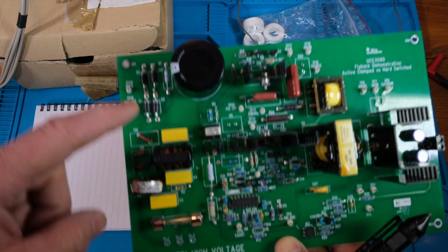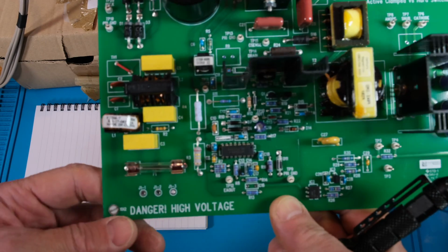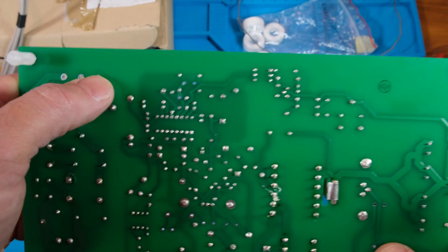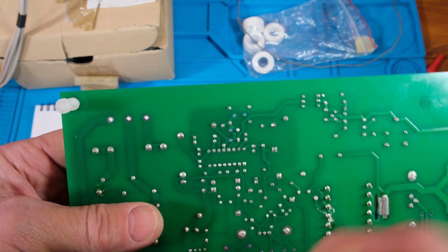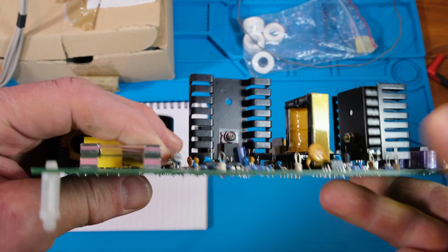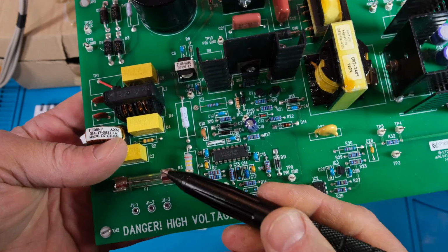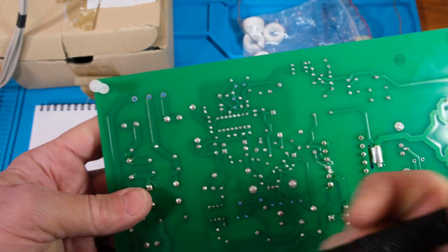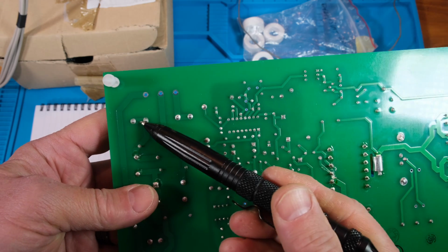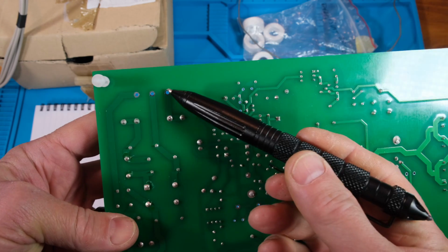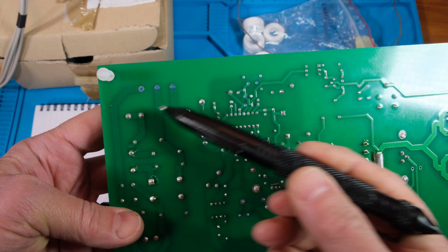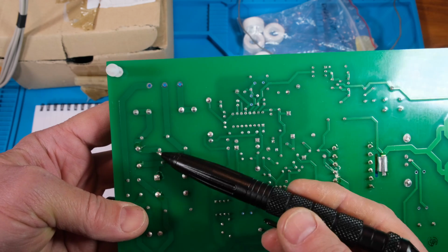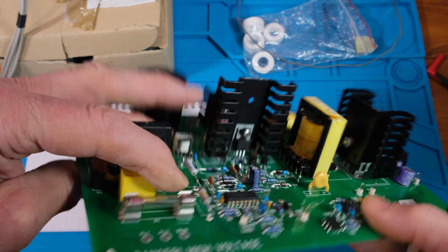So we have to go through our EMI filter, right? So let's look at this. We're going to see what these pins do. As I flipped over, this pin over here on this side comes down and connects to these two pads. And that's this side of the fuse. So the fuse comes over, and so come down here, jumps over the fuse, comes over here. So this is, say, the line voltage coming in here, the current, and it comes over here, and then goes through this circuit. And then there's a break right here.